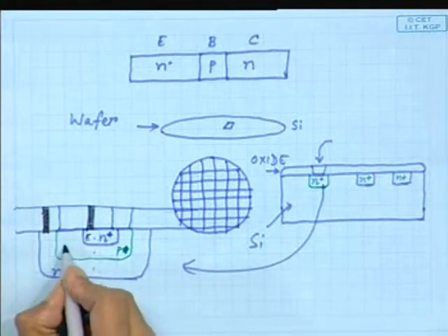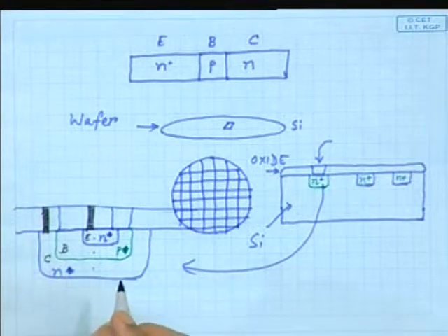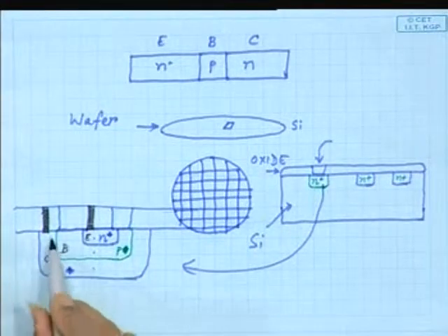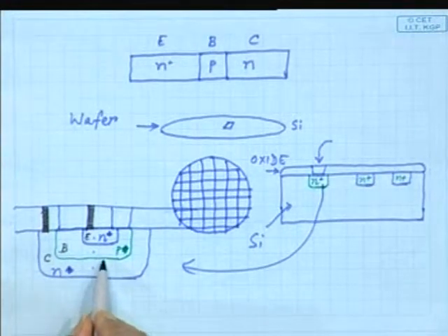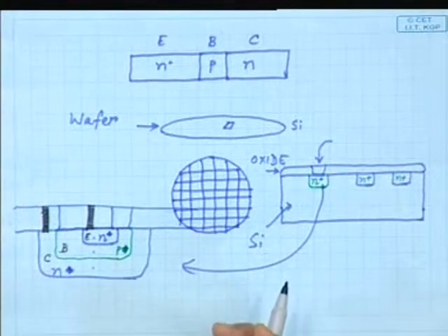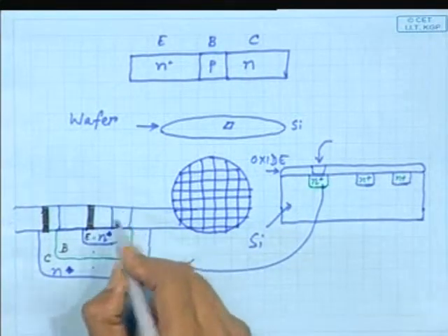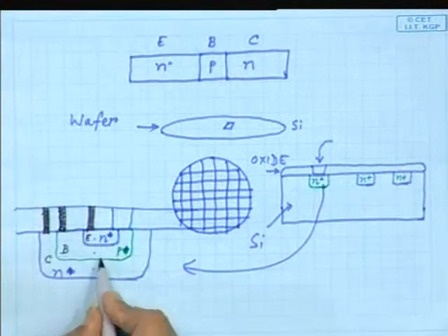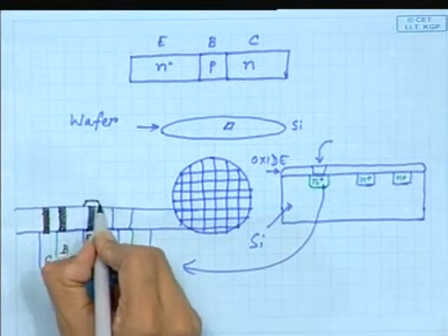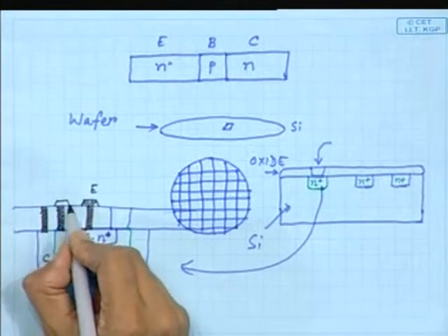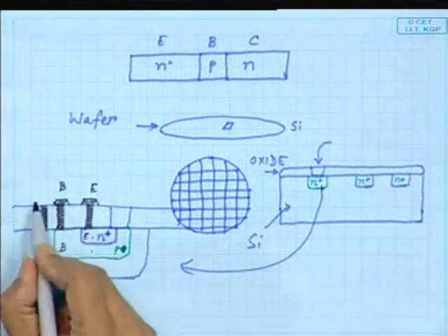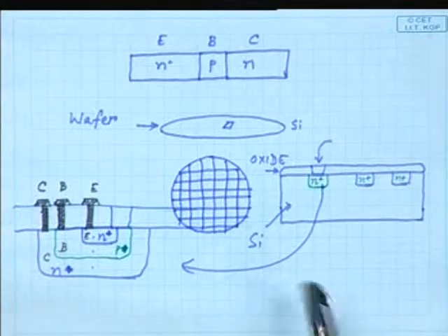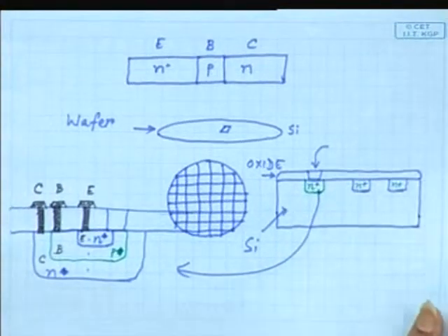So now this is your emitter region, this is base region, this is collector region, and you have to make this base region thin, which may be not properly scaled in this drawing, but you have to control all the parameters like doping concentration, temperature, etc., so that you can achieve the required height of the junction or the depth of the junction. Okay, so now this will be the emitter connection, all whatever I am drawing in black is metal, this is collector. Okay, so in that way you can make a bipolar junction transistor.